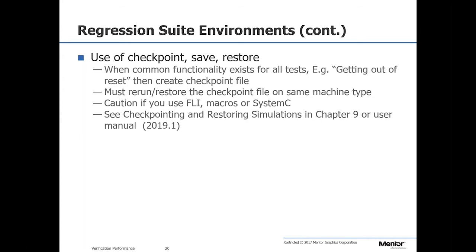The easiest use for this is disaster recovery. It's good if you have a simulation that takes hours or days to run. If you've got something that takes 5 days to run, it might not be a bad idea to set it to create a checkpoint after every 4 hours of simulation.